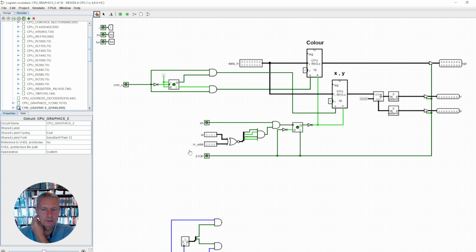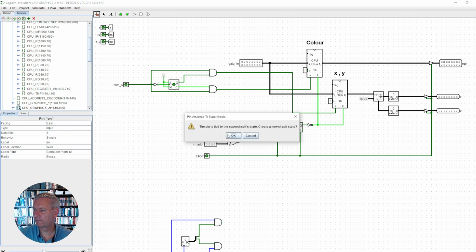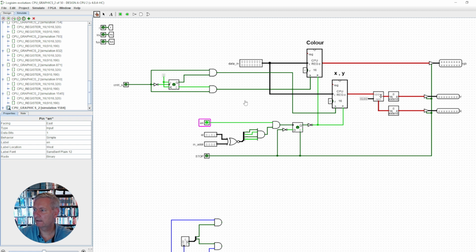The command pixel comes in, and the first part of the command is the 16 bits which chooses this card. So in order to choose the card, this value here will be sitting at high, and say for example, that would be a 1 and a 1. So these are now true. So when these are all true, you see this is going live, and this little point here is going live. Okay, so that's all we're really bothered about for the first part. It just picks the card.